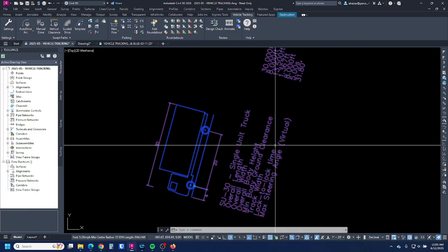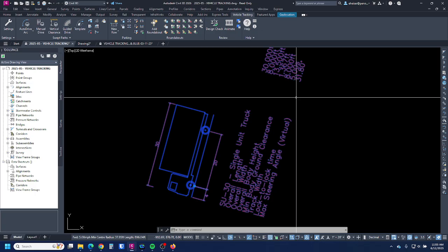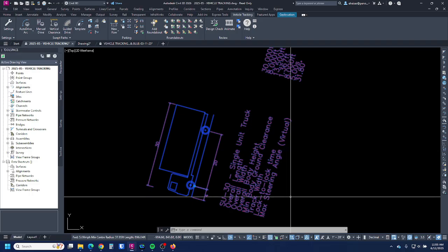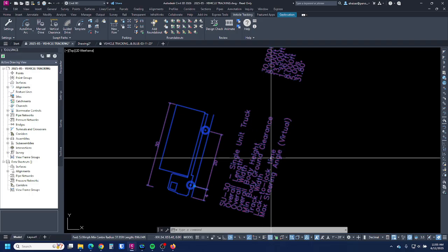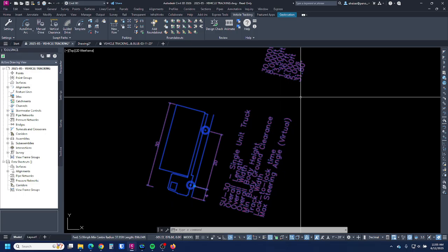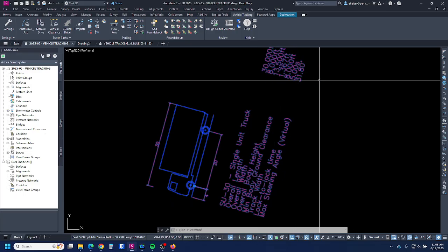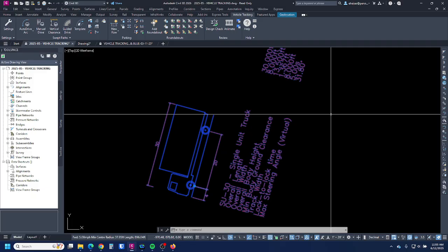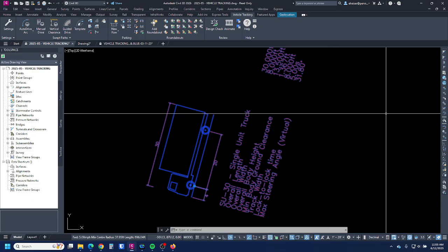Just a quick note, I talked earlier about the turn on spot setting, and what that is doing is eliminating the lock to lock time when you draw the movements. What that means is if you have the steering wheel turned the entire way to the left, the software assumes it takes you 5 seconds to turn it all the way to the right as you're moving the vehicle.